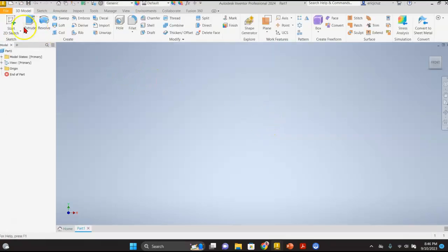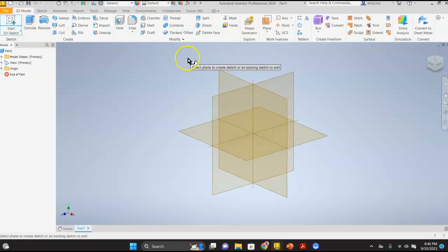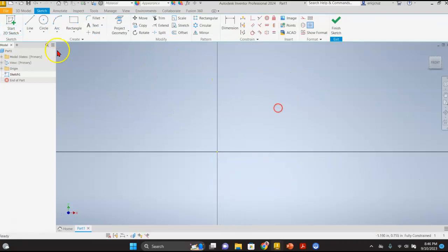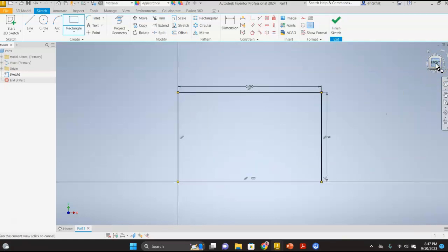And you should recall from last time we clicked on Start a New Sketch and we clicked on XY Plane. Then we started with a rectangle, and that rectangle was 2, so type 2, tab over 1.25, press enter, and then click on the front button on the view cube. So your length from left to right is 2 and your height is 1.25.